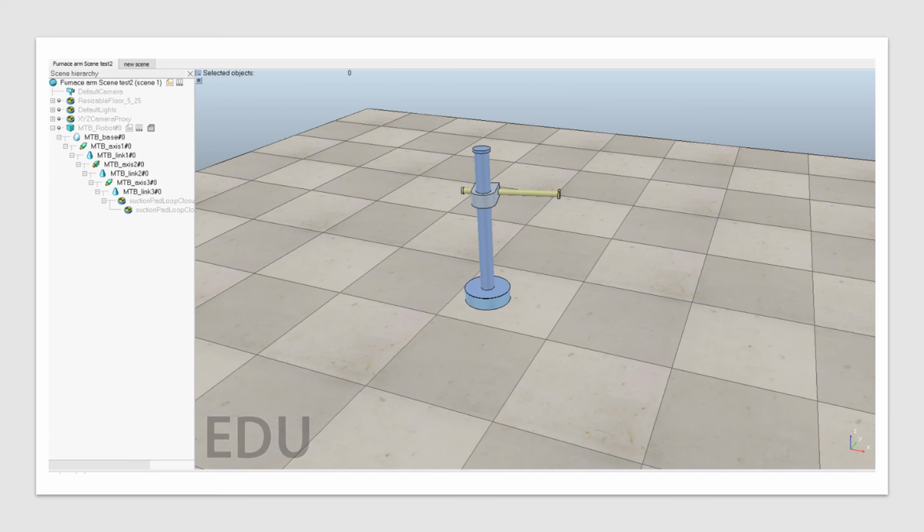This robot has also been imported into VREP, and the joints have been made so that it can be simulated in VREP. By simulating it in VREP, what we are doing is finding out if there are any errors, if the robot can be functional, and so on. So once the robot is imported, we need to make a child non-threaded script and then add factors such as angular acceleration, angular velocity, and linear velocity, and then set target values so that we can use the robot.